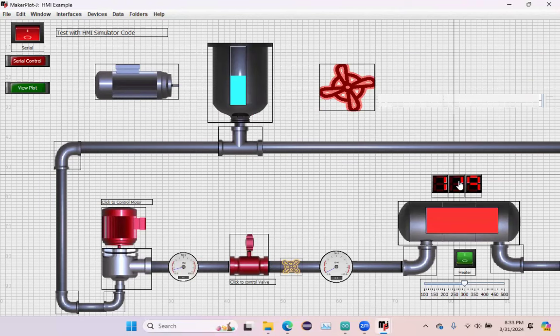But yeah, you can come up with a variety of images that will show various states of some system. And based upon a value, 1 to 10 or 1 to 5, whatever it's going to be, show different states of that operation of that component with different images. So we can see flames low, or flames high, or flames even higher, or flames out for our different images based upon a value of 0, 1, 2, 3, 4, whatever, and be able to cycle between those images automatically. So that's great for HMIs for the animation purpose, having those different images being assigned to it.